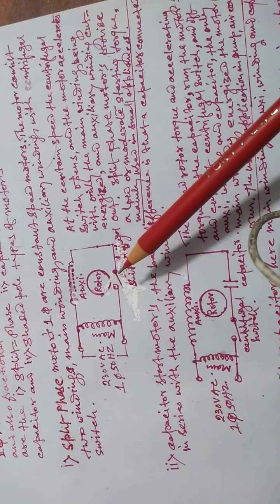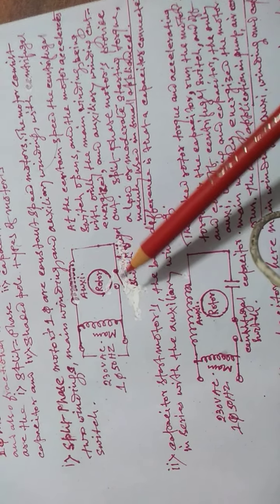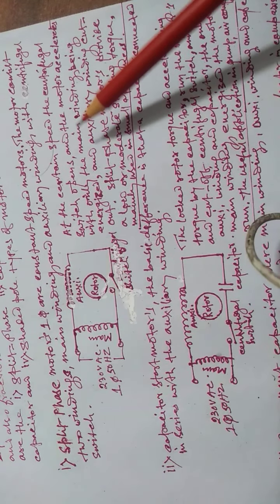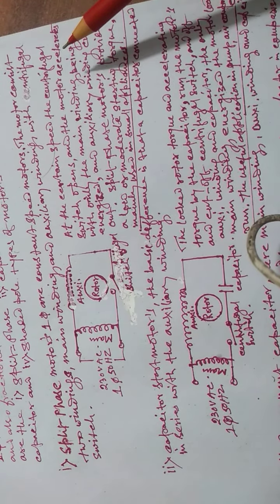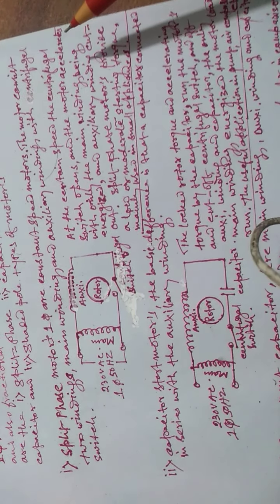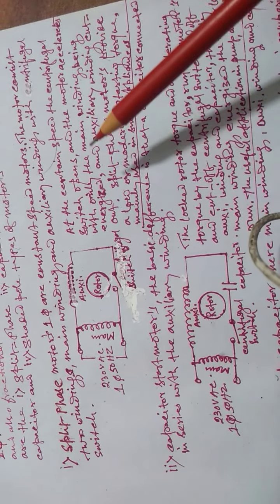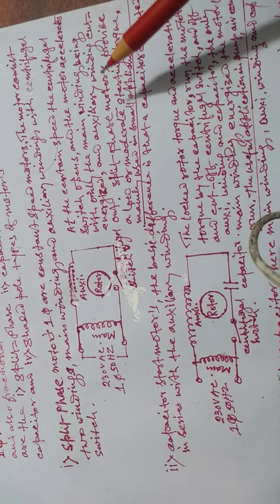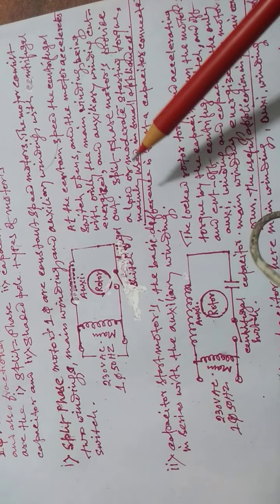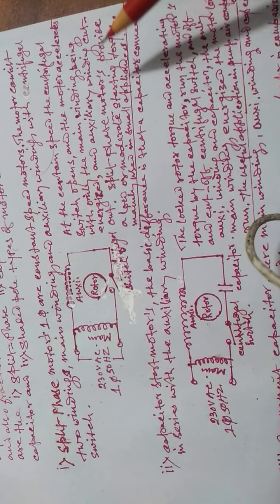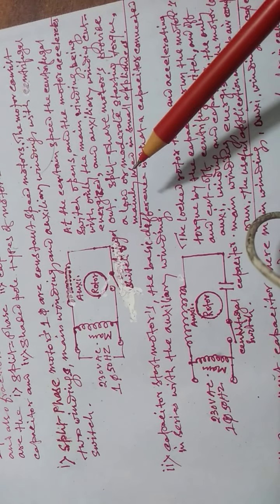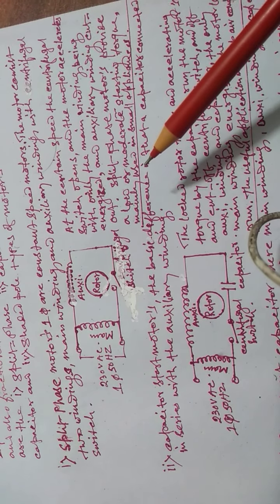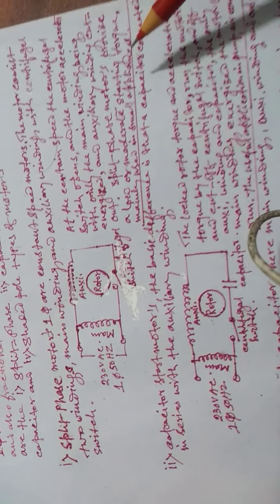These switches are open, but normally this centrifugal switch is closed. The motor operates with only the main winding being energized. The auxiliary winding is cut out. Split phase motors provide a low or moderate starting torque, mainly used in small applications.